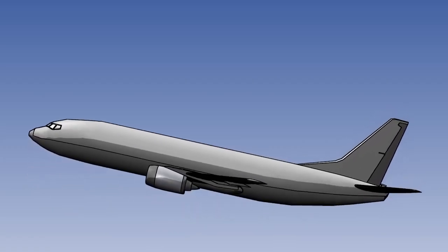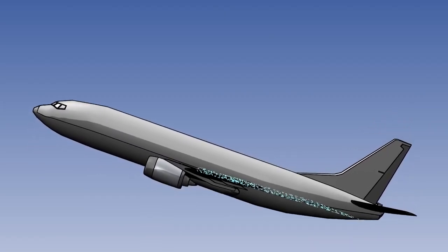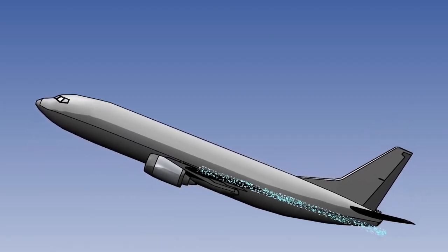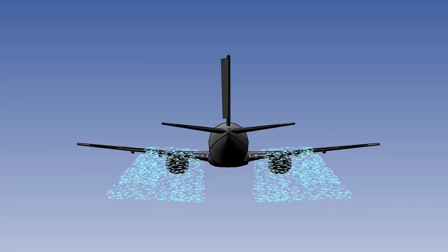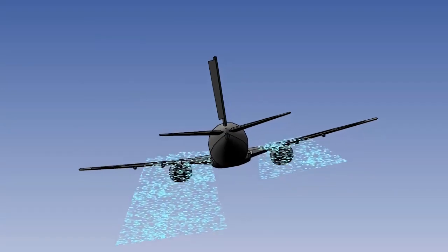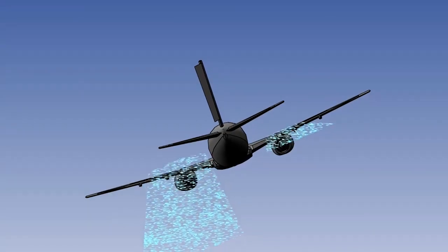Pilots should be careful not to pitch up too quickly, as this may restall the wing, even at a higher speed, which is known as a secondary stall and is covered in detail later in this series of lessons. The rudder should be used with great caution at any time when stalled or close to the stall, because of the possibility of causing a spin, on which more later.